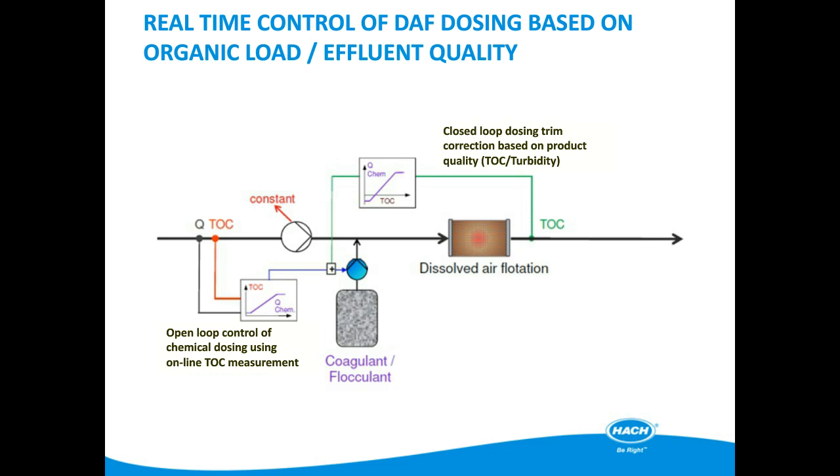Just going back to the TOC analyzer, Hach's Biotector TOC is, in our opinion, the best in the market for the challenging conditions of high solids loading that can be found in a DAF tank, as it is able to ingest and digest soft particles of up to 2 millimeters in diameter, giving a true TOC value. If the loading is exclusively in the solid phase, then the Hach Solitax probe is more than capable of making the solids measurement and requires minimal maintenance.